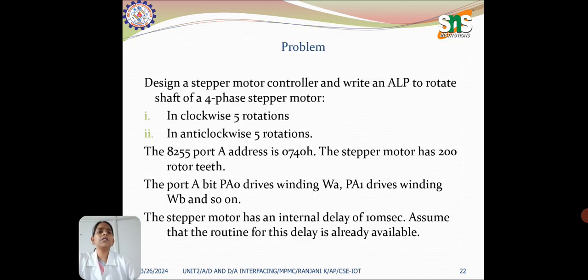Next we have a problem of designing a stepper motor controller. Write a program to rotate a shaft: clockwise 5 rotations, then anti-clockwise 5 rotations. The 8255 port address is 0740H. The stepper motor has 200 rotor teeth. In port A, PA0 drives winding WA and PA1 drives winding WB, and so on. The stepper motor has an internal delay of 10 microseconds. Assume that a routine for this delay is already available.